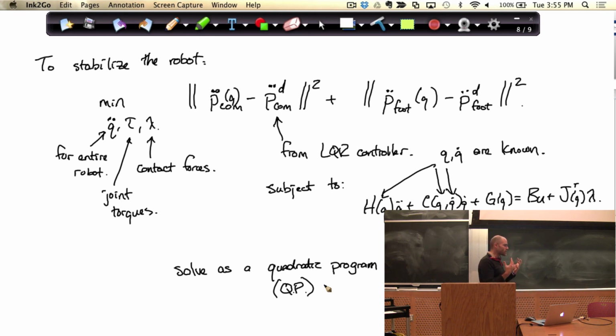It turned out to be easier to plan my contact forces first and then reason about what my robot had to do to make that contact work. So if I'm thinking about a parkour robot that's about to jump around this room, the extrapolation of this would be: don't think yet. The first thing you should think about is not how my leg is going to clear that. The first thing is, if I'm going to get over there, I'm going to need to put some force right around where you guys are sitting. Sorry about that. And then I'm going to put a little bit of force over there, and a little bit of force over there. And then in a second pass, I'll clean up and figure out what my robot had to do to make those forces happen.